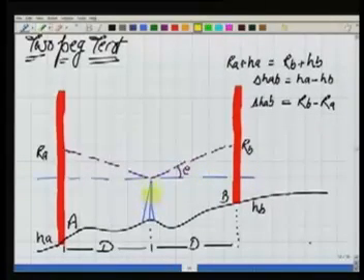The level is looking at an angle. The angle value is E, which is the error. So this E is nothing but the angle between the line of sight and the axis of the bubble tube; they are not parallel, rather they make some angle. That's the E, and we want to check whether this is so in our instrument or not.